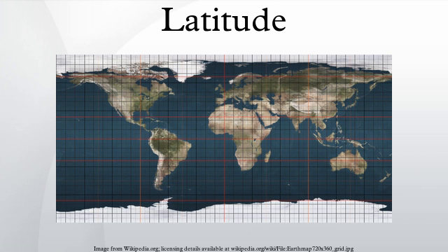Astronomic latitude is calculated from angles measured between the zenith and stars whose declination is accurately known. In general, the true vertical at a point on the surface does not exactly coincide with either the normal to the reference ellipsoid or the normal to the geoid. The angle between the astronomic and geodetic normals is usually a few seconds of arc, but it is important in geodesy. The reason why it differs from the normal to the geoid is because the geoid is an idealized, theoretical shape at mean sea level.